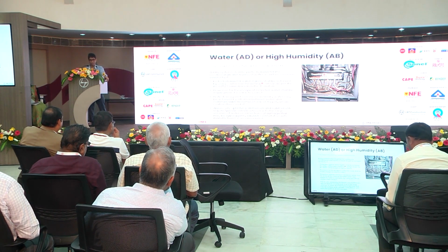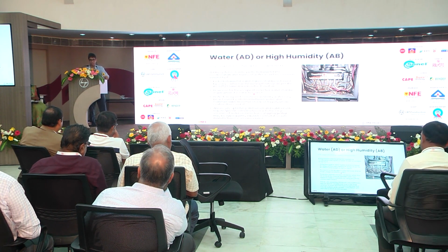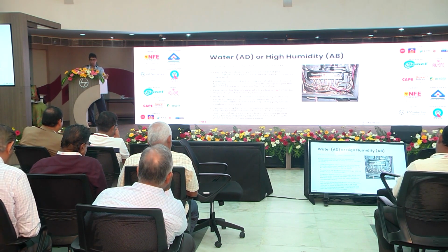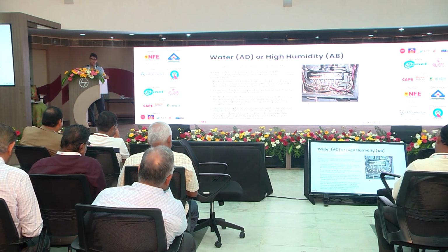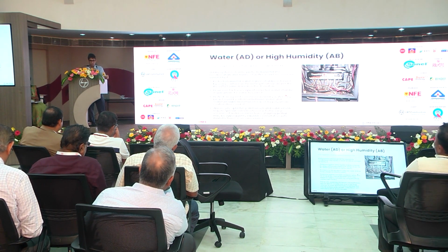So how do we protect against this? See, there are IP ratings as per 60529, and depending on the nature of water, whether it is a small amount of water, there are droplets, immersion, submersion, etc., there are IP ratings, these have to be selected. If water is going to be collected, let's say it is near a marina or something like this, it is very important that there are ways for the water to escape.